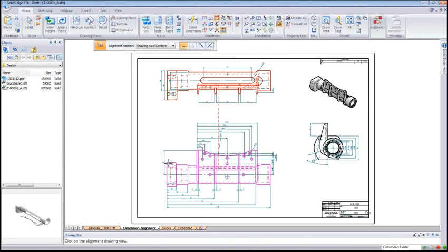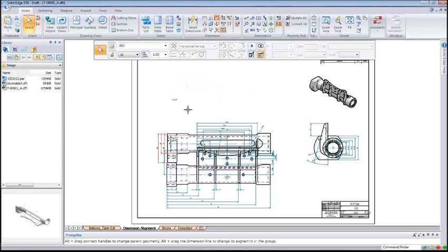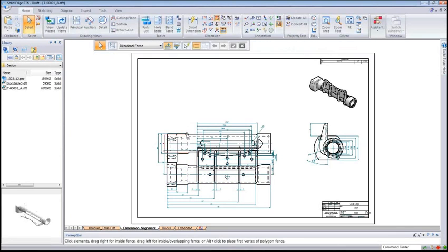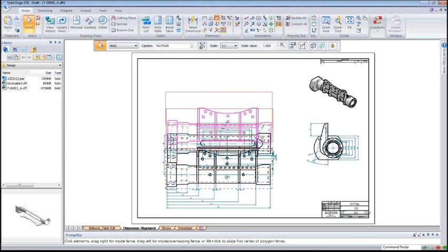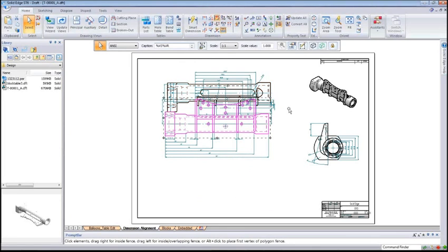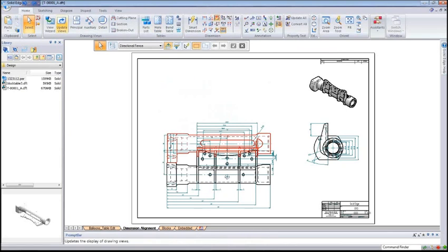So, once more, let's try this one more time. Right-click, create an alignment, and let's see, click on the alignment drawing view. I've already done that. And I don't want view centers, but I want my key points, and I want this key point to that key point. And now they should be aligned. So as I grab my view, which I'm having a little difficulty grabbing, here it goes. Oh, I actually got them touching. Anyway, point being is that now we can align by key points, which is kind of cool. I messed it up, but it works.